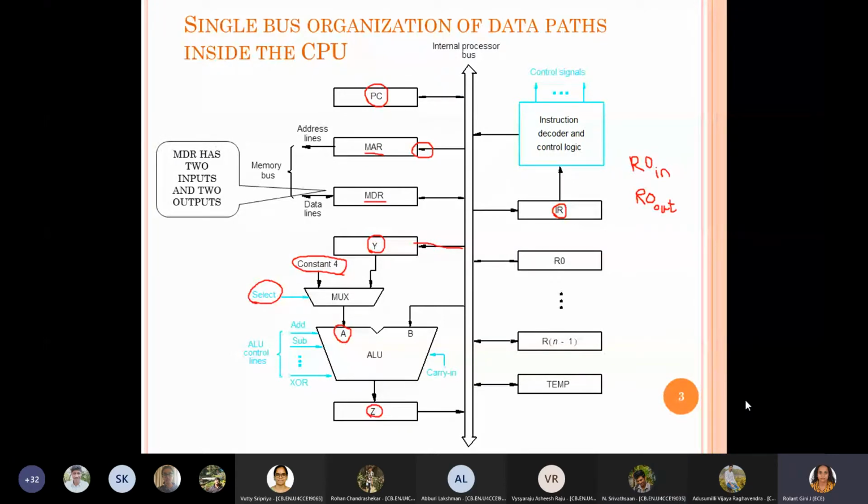Okay, when we are trying to read some data from the memory, for example, I am giving an instruction like MOV R0 within brackets, and then R1. If I give it without the square brackets, it simply moves the value of R0 to R1. Always the notation followed in your textbook is that what comes first is the source and what comes last is the destination.